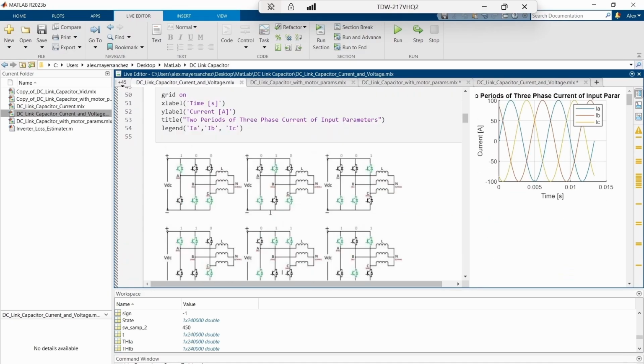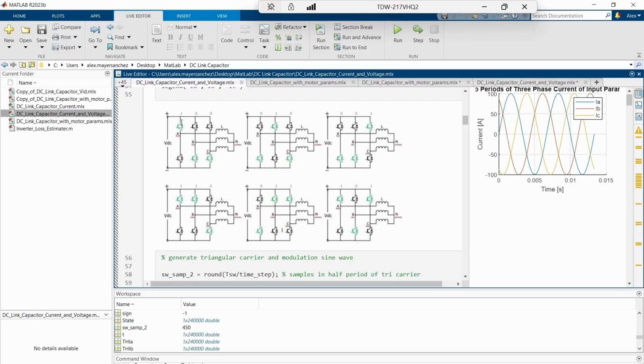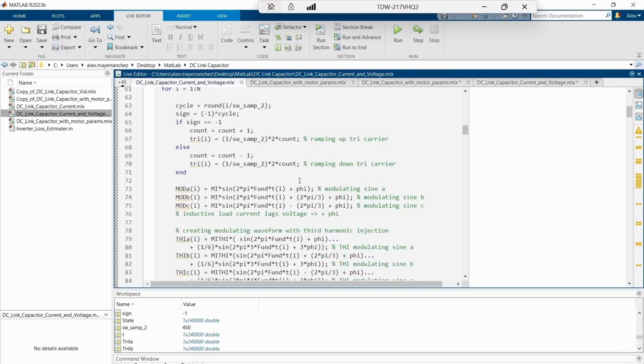And so you can see from this photo, these are the 6 different voltage vector states, but you can imagine if all the high side switches are on, then the potential at each of these pole voltages is the same as if all the low side switches are on. So there's going to be no current applied to any of these loads, or no voltage across any of these phases basically, and there's going to be no driving potential.